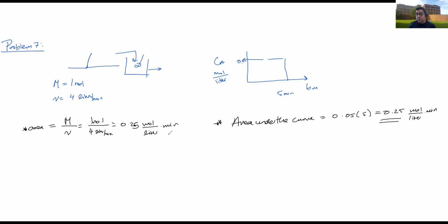These two values are equal, right? 0.25, 0.25. So this means that the mass balance is okay, and results are consistent. So once they are consistent, you're asked to calculate three parameters. First one is the average time, the volume of the reactor, and the experimental curve.